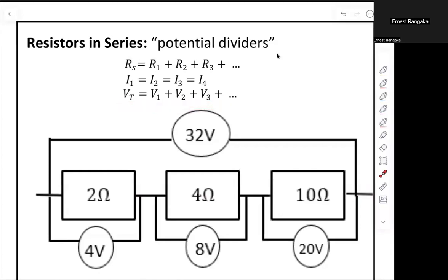So basically, when you get to university, they usually refer to it as Kirchhoff's voltage law and Kirchhoff's current law. In this case here, we can see a little bit of Kirchhoff's voltage law in action. They don't necessarily call it that in high school, but you can see that I've got the voltmeter reading around here, voltmeter reading around there. If you add those up, it's going to equal the voltmeter reading across the entire space, right?